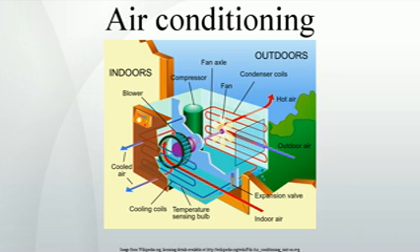Common storage media are deep aquifers or a natural underground rock mass accessed via a cluster of small diameter, heat exchanger-equipped boreholes. Some systems with small storage are hybrids, using free cooling early in the cooling season, and later employing a heat pump to chill the circulation coming from the storage. The heat pump is added in because the temperature of the storage gradually increases during the cooling season, thereby declining in effectiveness. Free cooling and hybrid systems are mature technology.